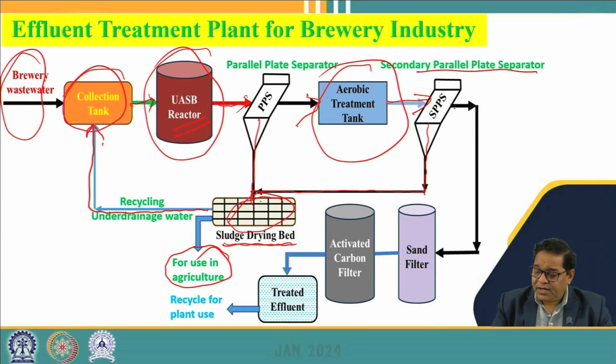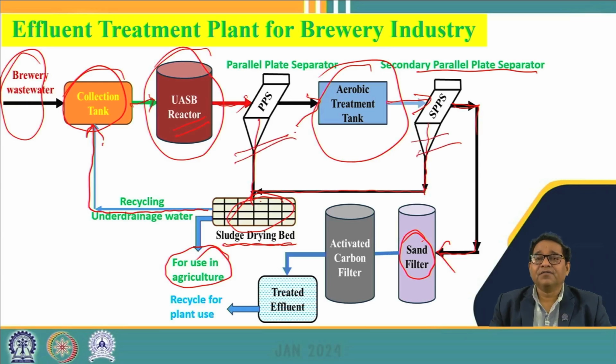After the biomass is separated from the treated effluent, it is taken for filtration in rapid sand filters. A rapid sand filter is provided because even after settling of the entire treated effluent, there can still be a lot of finer suspended biomass. They are filtered here through the sand filters.